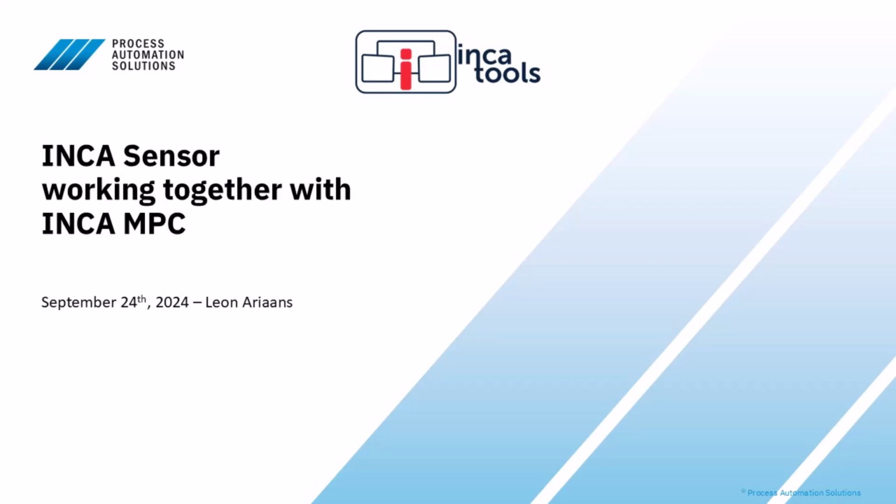I don't know if I understand the question completely. I read this as analyzer data coming in on a regular basis, and on top of that you want to add lab samples. Is that how I should read this? That's how we read this. Okay. If you currently want to do that, then what we do is apply two sensors: one that handles the updates from the analyzer, and another one on top of that that updates that sensor based on the lab sample values that we get.